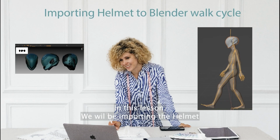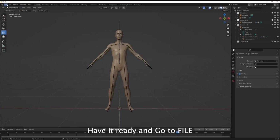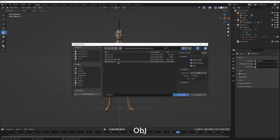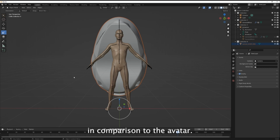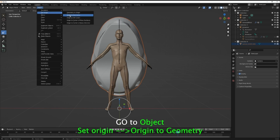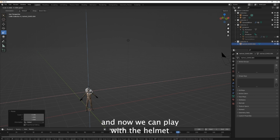In this lesson, we'll be importing the helmet into Blender to fit on the avatar's head. Go to Blender, open your FBX avatar, have it ready, and go to File, Import, OBJ, and Helmet. You'll notice the helmet will be a huge size in comparison to the avatar. For this, go to Object, Set Origin, Origin to Geometry. And now we can play with the helmet and resize it.